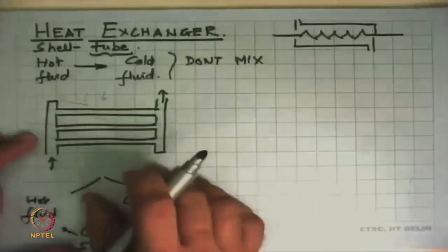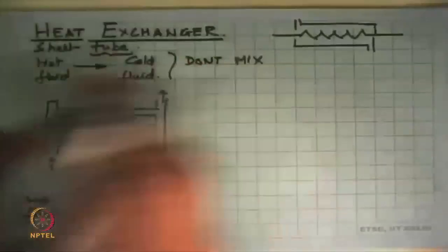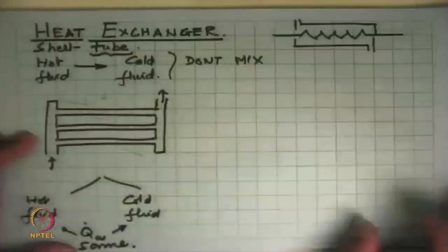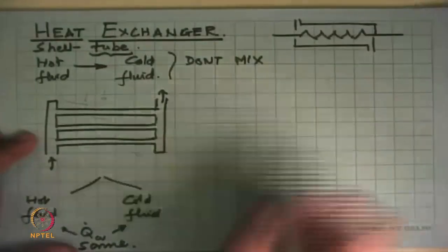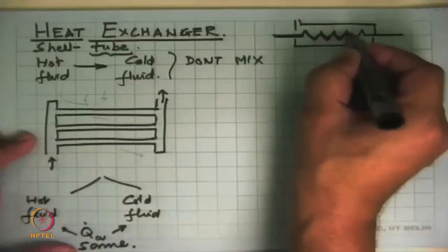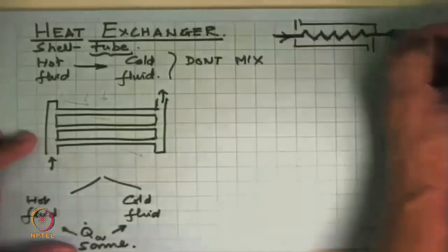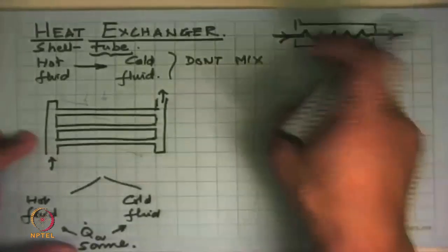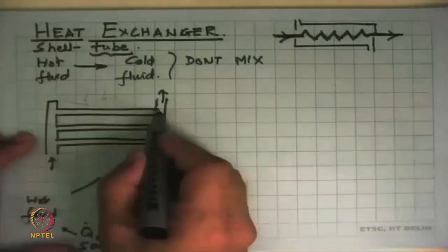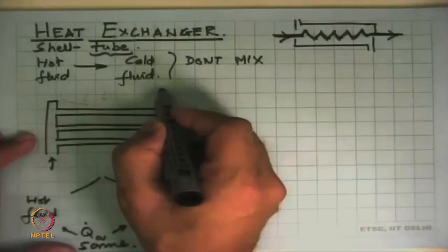The thermodynamics knowledge tells you how much your pressure and temperature are going to be, no matter what the mechanical design or the thermal design of the exchanger. The common symbol is shown here, with zigzag lines. These zigzag lines denote that one fluid comes in here and goes out here, and in going so, it could go through many parallel tubes, or maybe some are in series, and then connects again and goes out.